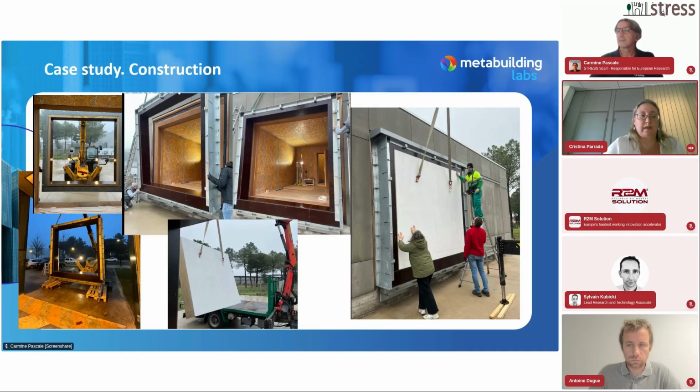How do we put this test, or how do we connect it with our cell? We have developed what we have called the sample holder frame. This frame is where we mount all the components that we are going to test. It's a steel frame that is reinforced mainly at the bottom. Inside we have an inner frame made of wood and insulation, and this frame, as you can see, can be removed and replaced.